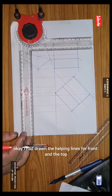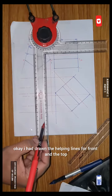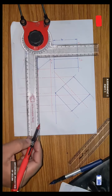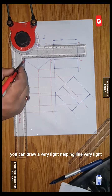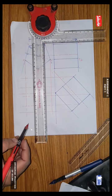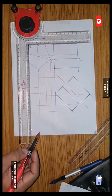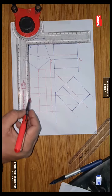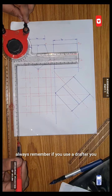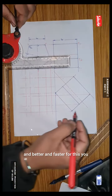Okay, I had drawn the helping lines for the front and the top face. You can draw a very light helping line, very light. Okay, this also, this line. Always remember, if you use a drafter, you will get a better result and better and faster work.